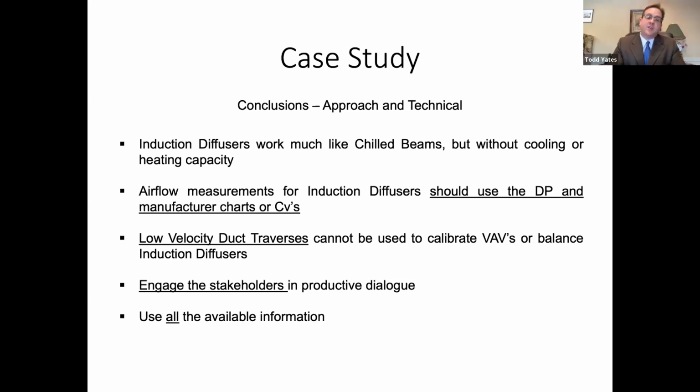Yeah, well, actually, we did use both Evergreen and Shortridge instruments on this project. I didn't mention that, but that's one of the first things we thought: even though our equipment is calibrated, could it have been dropped? I mean, things happen. So before we contacted any of the other stakeholders about the issue, we sent another technician to the project with not only another set of equipment, but the other brand, so that we could check that.